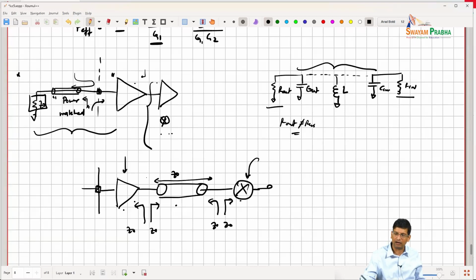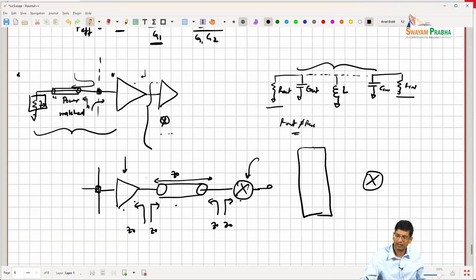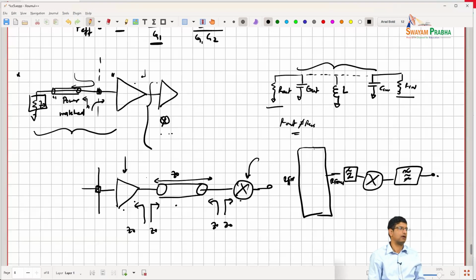You will see an RF filter. So because the array is RF in and then RF out, right? So you'd have a filter here going into the mixer, and then at the output of the mixer, you'd have an IF filter, right? So both these filters exist now in systems for various reasons, but this kind of stuff exists. But inside a chip, usually the resonant networks are enough.